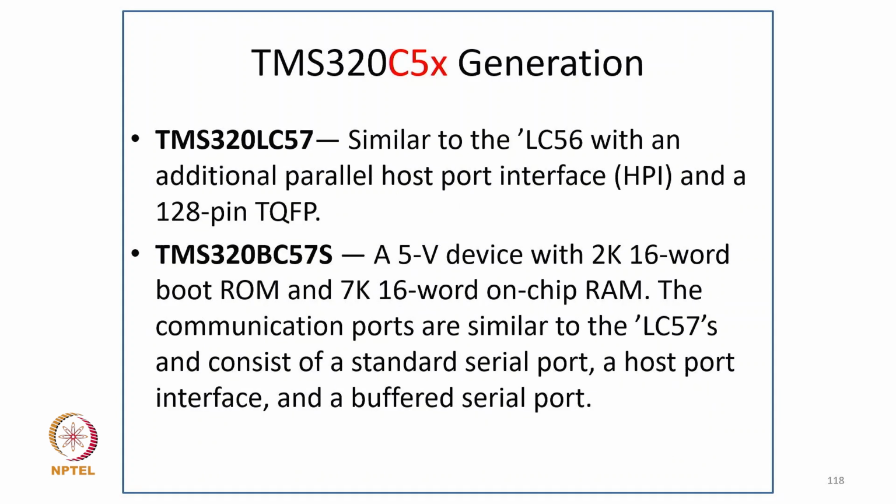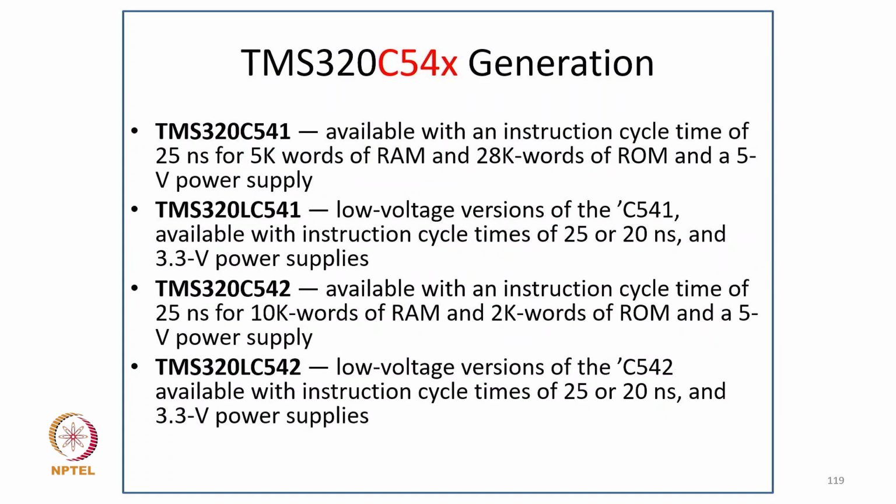TMS320LC57, similar to the LC56 with the additional peripheral host port interface HPI and the 128-pin TQFP, and TMS320BC57S, a 5 volt device, with a 2K 16-bit boot ROM and 7K 16-bit on-chip RAM. The communication ports are similar to the LC57 and consist of a standard serial port, a host port interface and the buffered serial port.